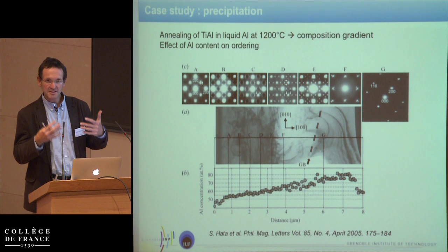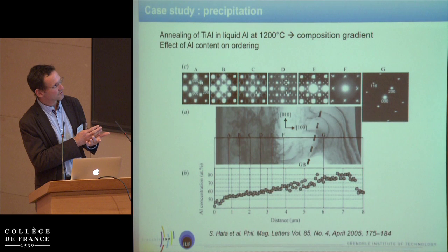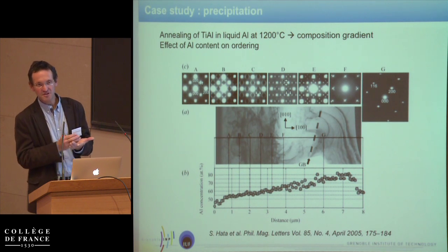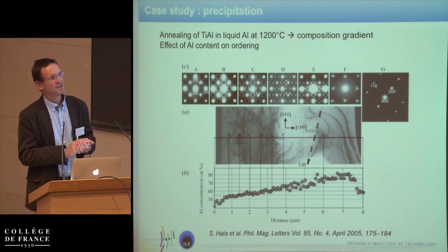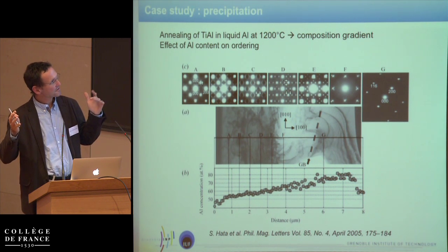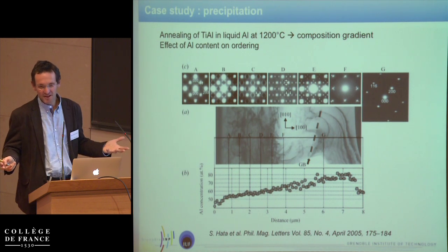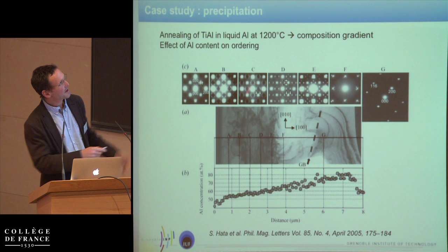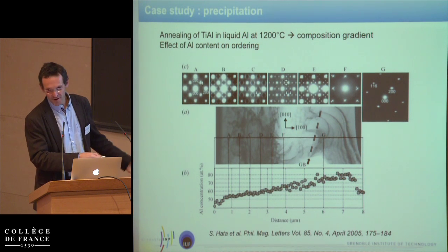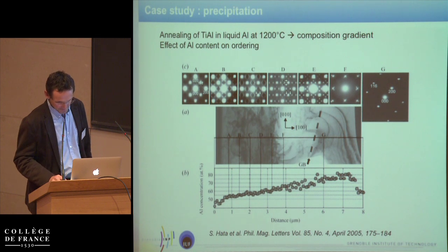So, of course, in this case, your ability to characterize the effect of composition on microstructure is restricted to very small scale microstructure, because you have a small scale composition gradient that restricts you in terms of microstructure development. So, of course, you wouldn't be able to look at recrystallization or grain size in these kinds of materials, obviously, because the scale is too small.